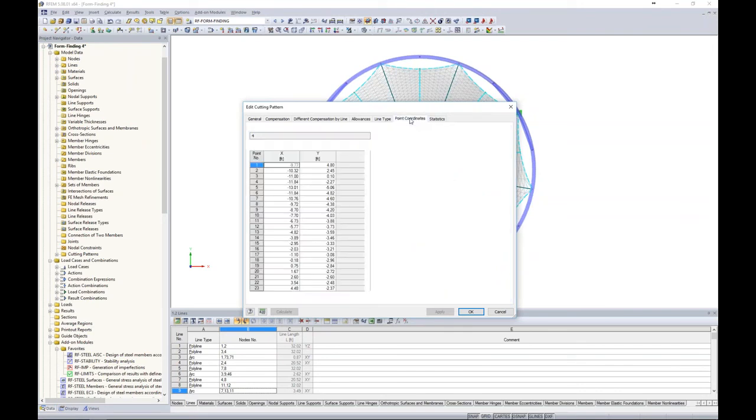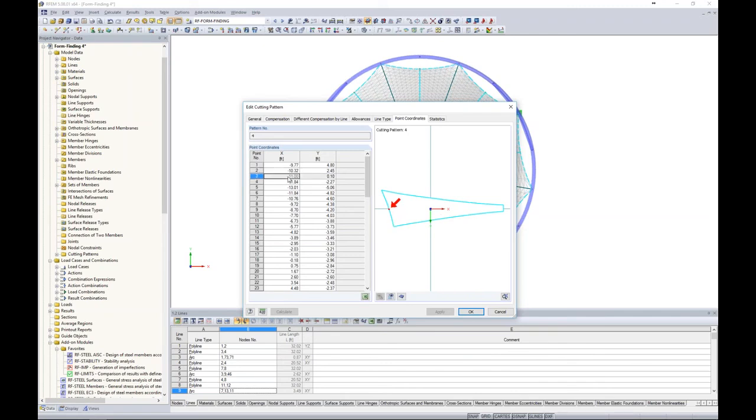So now we get a couple different tabs up here, which is our 2D cutting pattern. And once we run the calculation, we get the X and Y coordinates for our 2D pattern here. Now, this is a table, and as I scroll through this table, it is synced up to my little graphical view over here on the right. I can always zoom in, and it's all based around my origin right here at the center about what these X and Y points are.